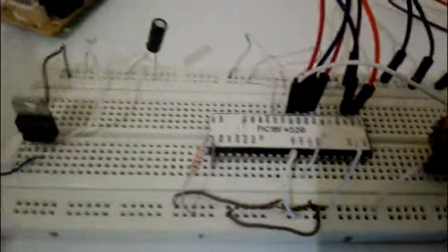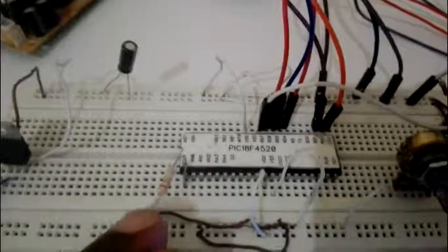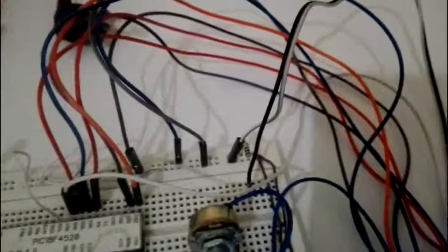So just an overview. We have the LCD, the potentiometer right there, and this is a 10K potentiometer. Then I have all the wirings. Then we have the 12K ohm resistor for the MCLR pin. Then I have a switch mode power supply that I'm using to supply power to this circuit. Basically that's it. If you follow everything we said, you never go wrong.